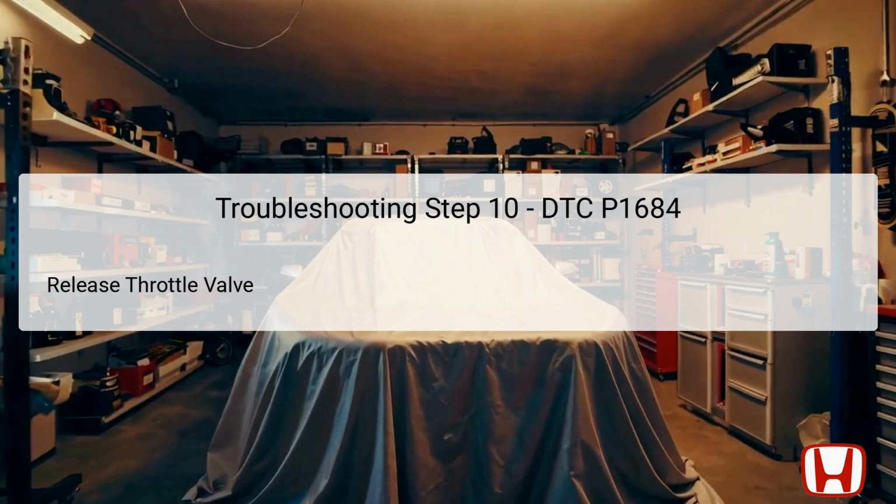However, if the valve doesn't return appropriately, the underlying issue likely lies deeper, potentially indicating a malfunctioning throttle body that requires replacement. This observational step is essential as it provides real-time feedback on the condition of the throttle system, directing the technician on how to proceed with repairs.